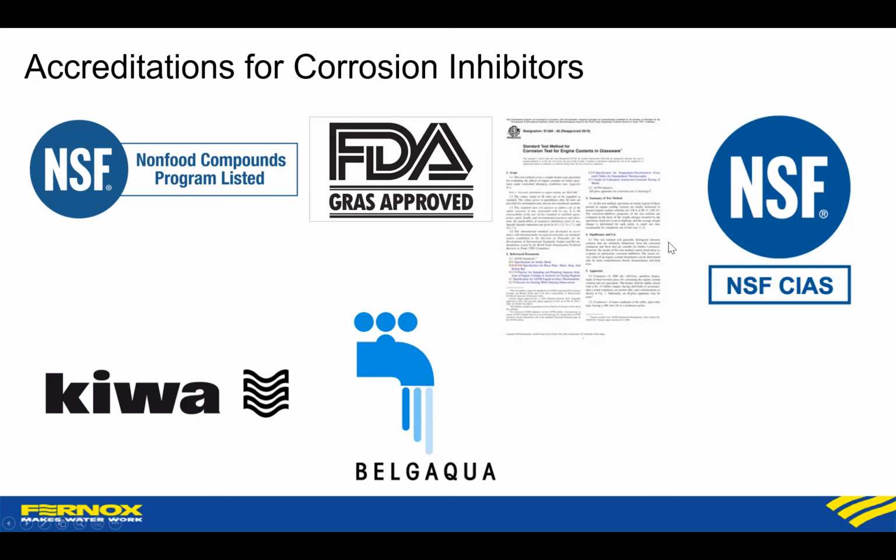I think they stand alone really globally. You've got an ASTM standard, which is mainly used in North America, and then you've got another NSF program, which was used initially in the UK, but it is now starting to spread. This ASTM standard D1384 is a reasonably good test methodology for testing heat transfer fluids, tests against cast iron, solder, copper and aluminium, I think. So a lot of manufacturers will quote that and will quote as they pass.